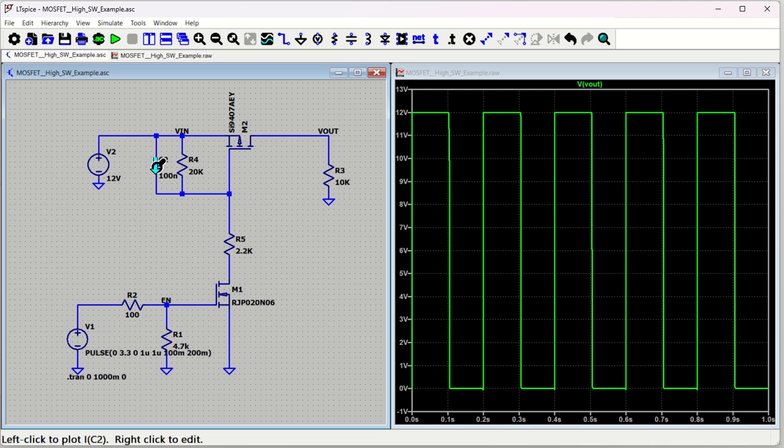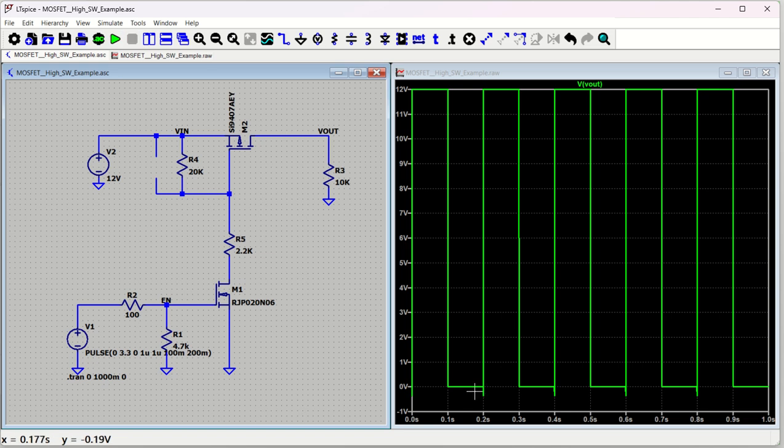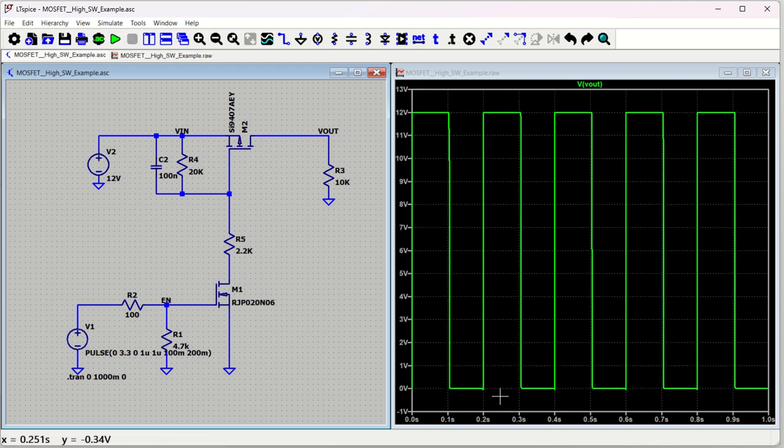Now what I told you is you just remove this, and let us run it. So you are seeing there is an undershoot at the output. Now if I keep that capacitor, which will help to charge the PMOS properly and put it in the proper situation, then this will be removed.